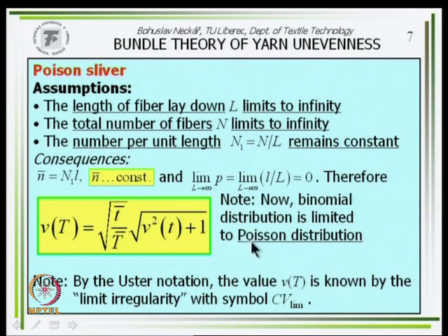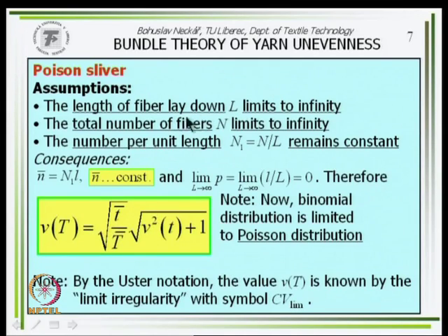Nevertheless, usually we can imagine the process of creation of sliver as a process which is actual on a very long length, capital L. Therefore, let's imagine that the laydown length, capital L, limits to infinity. The total number of fibers, capital N, is also limited to infinity.